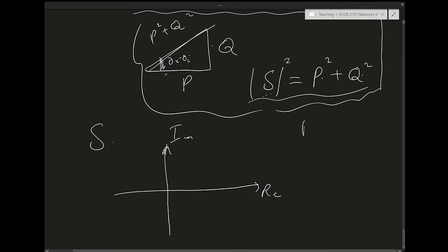That refers back to complex power, right? Because we said S equals P plus jQ. When we say it's a 4-quadrant supply, that means it's a supply that can generate S in all 4 quadrants, meaning we can have a situation where we have positive real power, the supply is supplying power, and positive reactive power. The supply is supplying reactive power. We could live in this quadrant. The supply could supply positive real power and absorb reactive power. The supply could live in this quadrant.